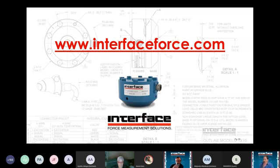All right. There is a question too about creep and whether that's the material itself or the strain gauges. Essentially, it's all the elements in the sensor. Everything mechanical will respond to creep. And thus the goal is to match the creep behavior of the bridge to the creep behavior of the load cell material or the flexure. So yes, creep affects both, but you want the end result to trend in the same direction so that you get minimal error or change in signal as a result of that.